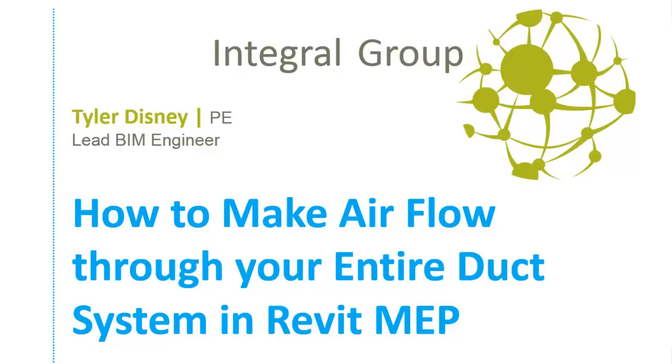Howdy, this is Tyler Disney with Integral Group Oakland, and in this video I'm going to be going over how to set up a duct system so that airflow information travels through all of the pieces, all of the families in the duct systems. A lot of times you'll start modeling a duct system and the airflow will go from the air terminal to the VAV box, but then somewhere along the line after that the ducts stop knowing what their airflow is supposed to be adding up from the air terminals.